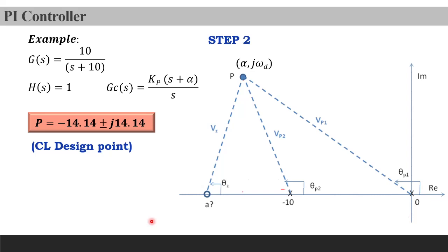So we discussed that if a point passes through your root locus, then you can say that if you substitute the values of that point into its transfer function, right, the forward path gain, you can always say that k times GS would have been equal to 1 magnitude plus minus 180 degrees, right?